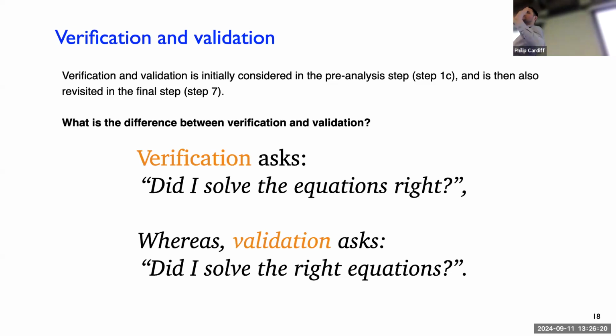So let's just assume the maths model is correct, that there's no temperature effect. So verification is things like, did I do a mesh study? Is my mesh fine enough? Or are numerical errors destroying the solution? So maybe you have the correct mathematical model, but you use too coarse a mesh, or you don't solve it with the right numerical settings. You have too large iteration error or discretization error, and you just get the wrong answer. So verification is doing those checks.